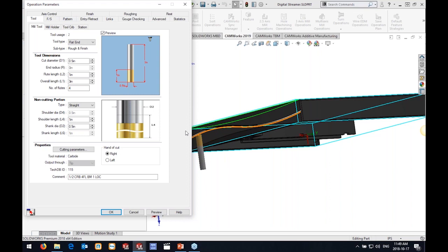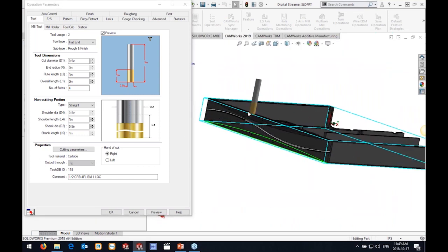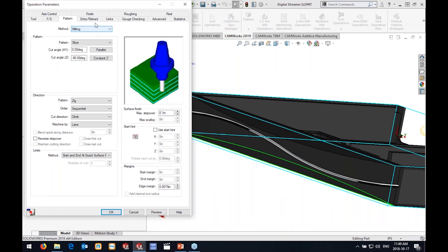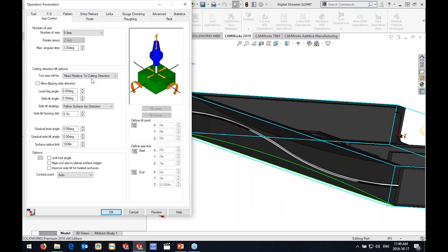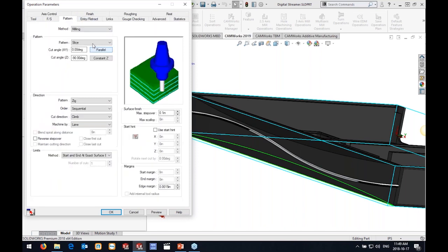We're just going to run a swath machining pass right down here. So we're putting it in the machine in this orientation. But on the pattern tab, rather than before, where I had to go to my tilted relative to cutting direction, specify my tilt angles, go to my pattern tab and specify probably flow line between curves or flow line between surfaces and everything else.